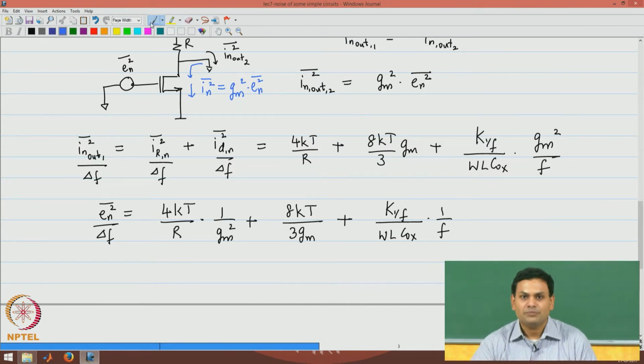More importantly, I have considered a short circuit at the output because the MOSFET is a voltage controlled current source element, so it is often very easy to think in terms of the device currents, and we know that currents tend to take the path of least resistance or least impedance. Therefore, if we short circuit the output, all of the current will flow through that output node, and the analysis simply becomes easier.